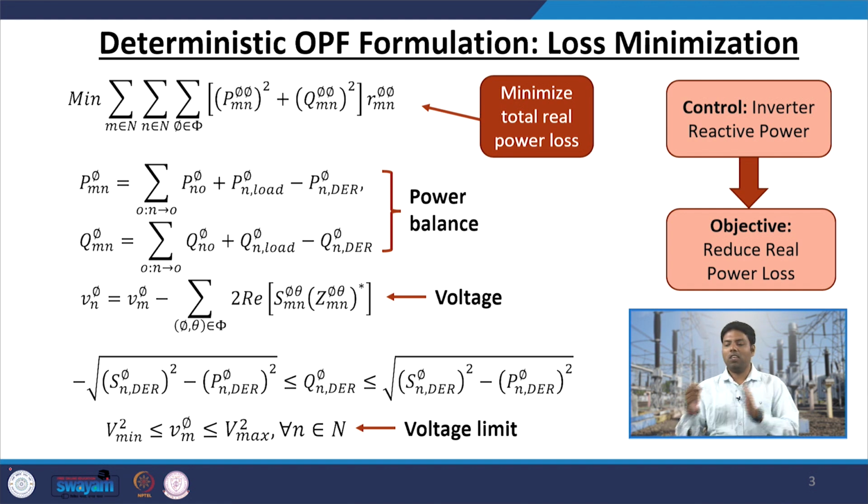From there we have generated the scenarios using Monte Carlo simulation or Latin hypercube or point estimation method, and after that we followed some scenario reduction technique so that Monte Carlo simulation will become easier to implement. Okay. So, today we will see how we can formulate the probabilistic OPF itself.